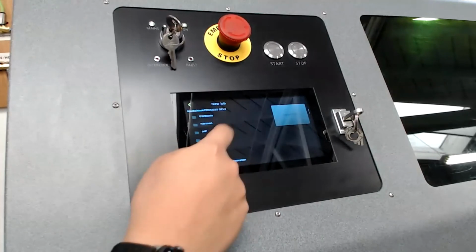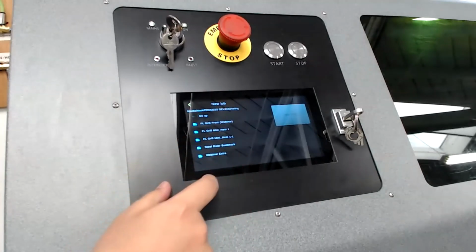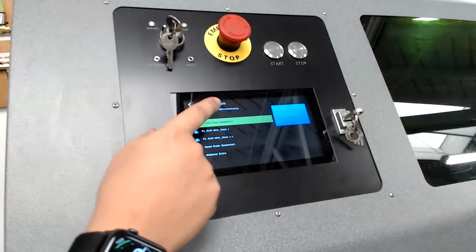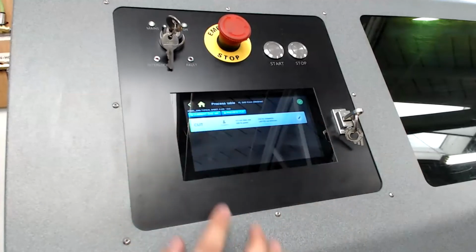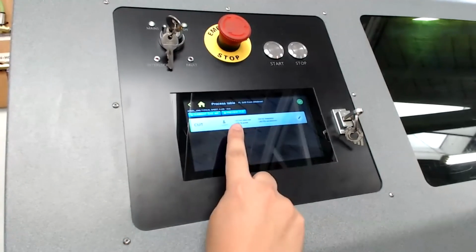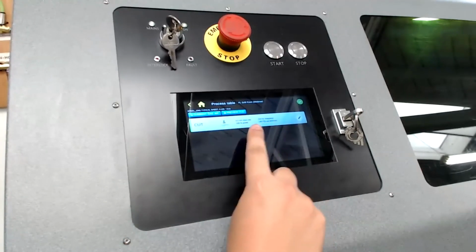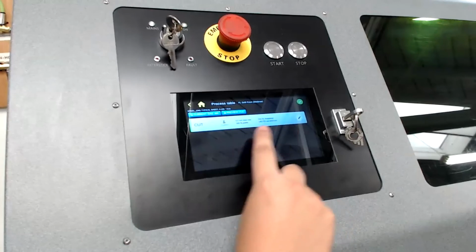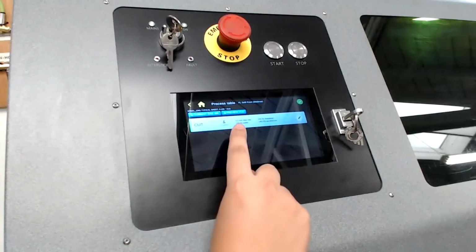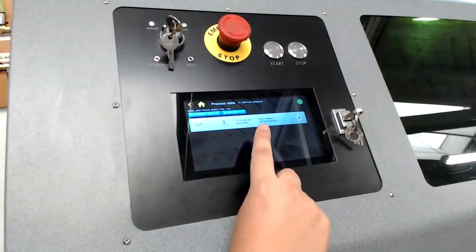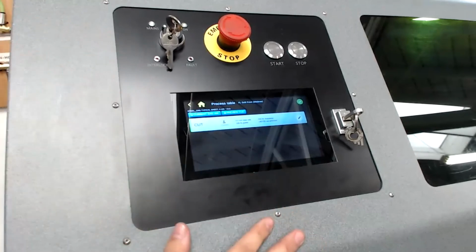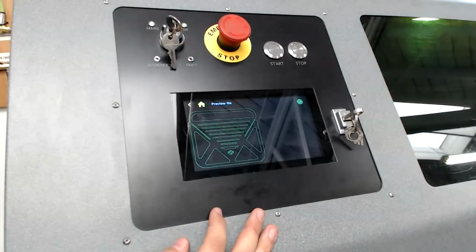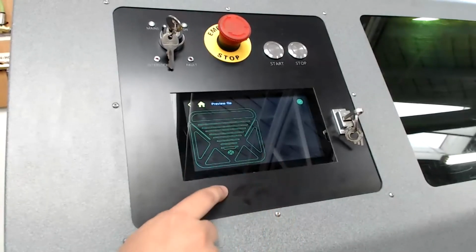We're going to go find our file. And then we're going to do the grill front for webinar. We're going to select our file. So now we see our cut information and this has all been imported now, matching up to our FabCreator file. So we already know what our feed rate is, what our power level is, our frequency, our pressure, everything is already done for us. There's no guesswork. You don't have to try to figure out what's going on there, right? And we can see our preview file. We can see the file that we're actually going to cut.